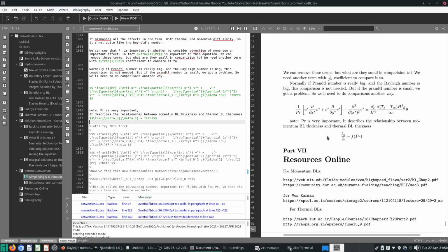So the last video we were trying to describe what's going on if the Prandtl number is very high. If the Prandtl number is very high within the thermal boundary layer, all these advection terms can just disappear, and they will not have a very big influence on the velocity profile. However, if the Prandtl number is very low, then the opposite effect will occur. We cannot just throw these terms away. We'll need to do something.